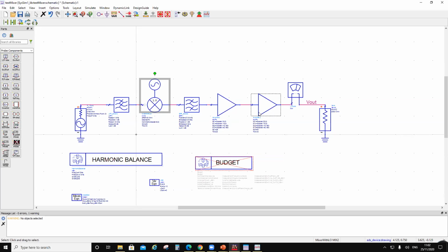So power delivered here is 30, gain is 50. So where is the gain computation coming from? I know what my linear out is. I know what my DAC is doing. If the DAC is doing minus 20 and I want 30 out, so what would I do? I should have a gain of 50 at least, right? So that's how I would compute gain.